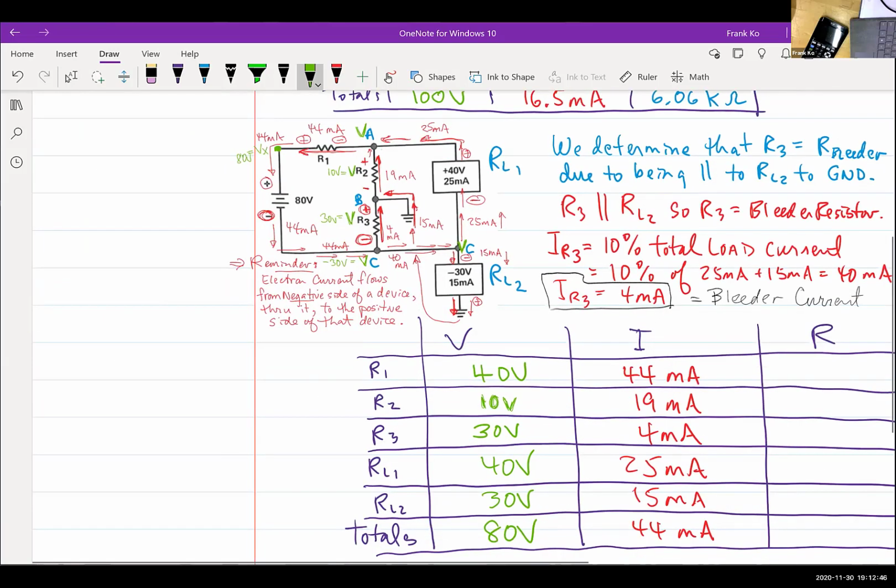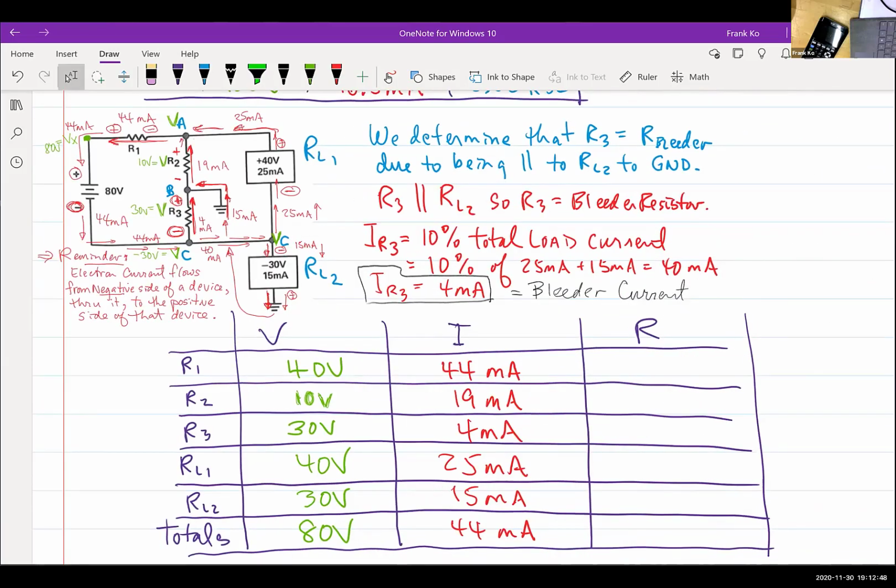Does that complete my voltage column? Yes. So we start off with current analysis. The currents allow us to mark polarities, because the current arrows tell you what direction the current flows and what polarities are found where. And then we find out our voltages. The only thing left is Ohm's law to determine your resistor values, yes? All right, so it's just V divided by I.